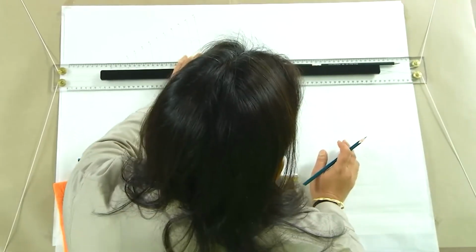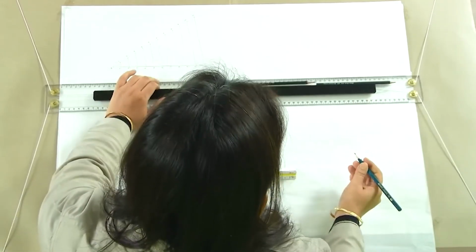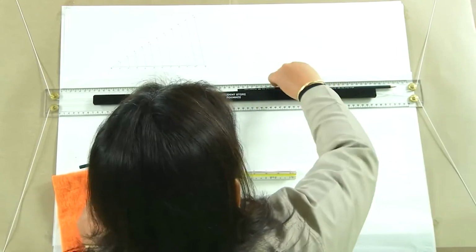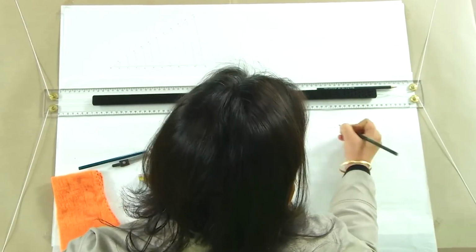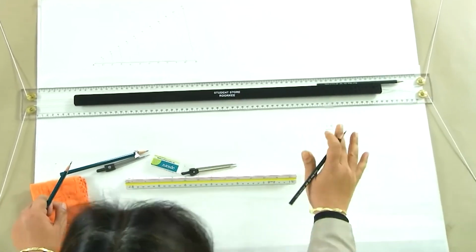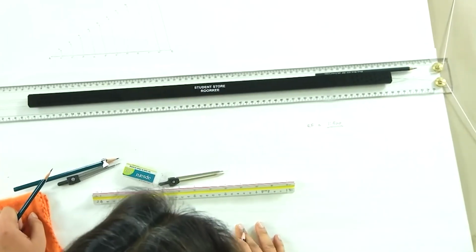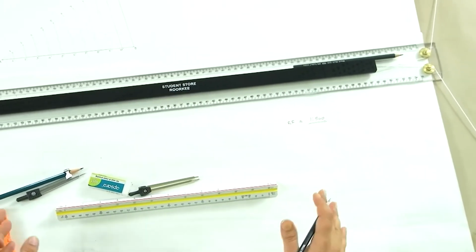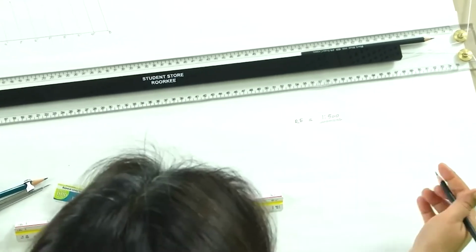So, now we are drawing the scales, both types of graphic scales, not the engineer scale of course. We are drawing the scale onto the sheet. Let us see how we do that. Suppose I am drawing a scale to represent an RF of 1:500. Now, if I have to draw a scale big enough to measure, say, 50 meters.